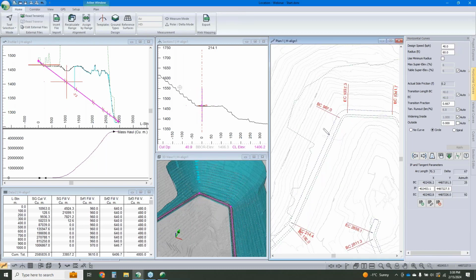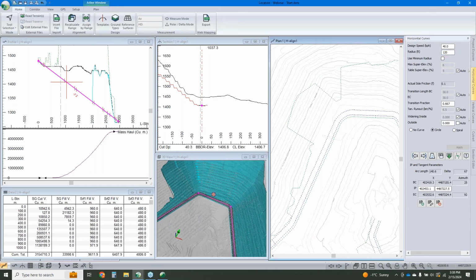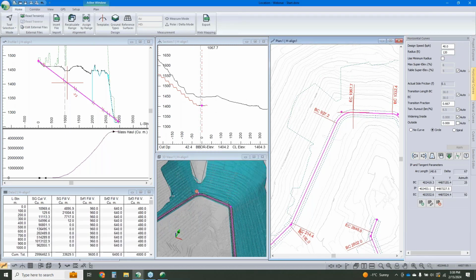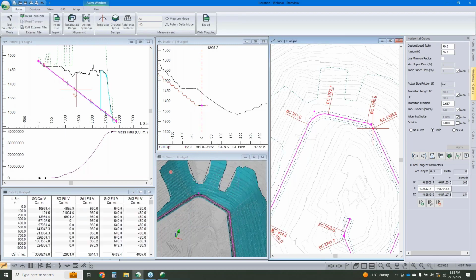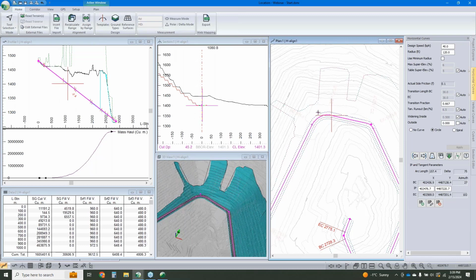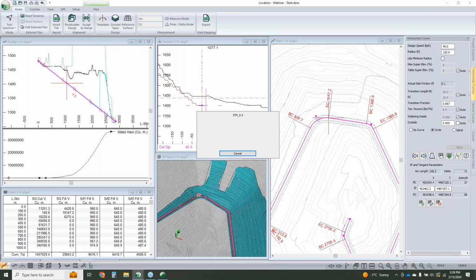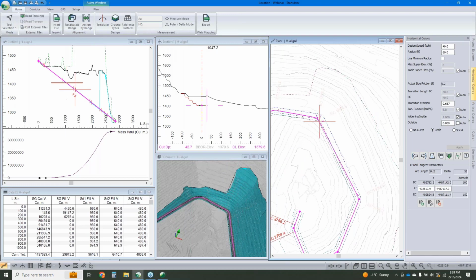And with this, we're going to have a nice surface that we can throw into machine controls. We can really get a feel for what we're dealing with. And let's pull this around. So again, these lines here are showing my slope stakes. I'm also looking at the 3D view. Pull these around, keep that away from the edge, pull this up this way a little bit. Everything's dynamic, so I can see the ground at center line updating as we move this around, and we'll keep pulling this.